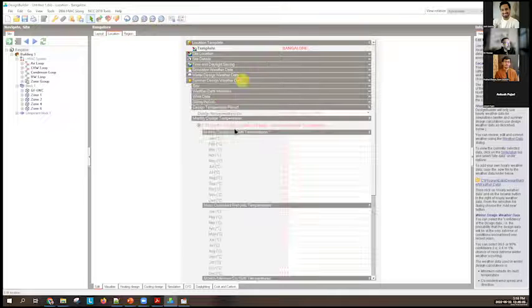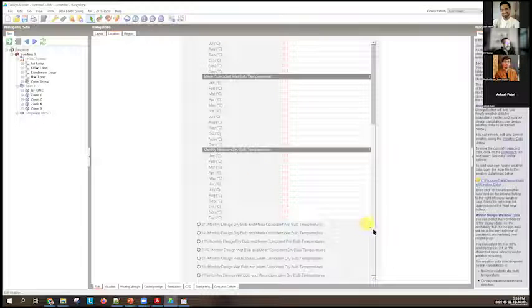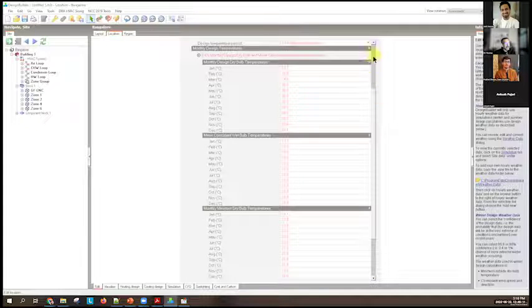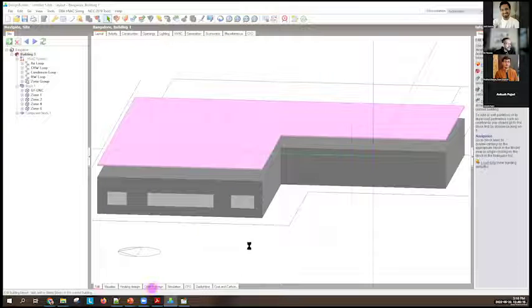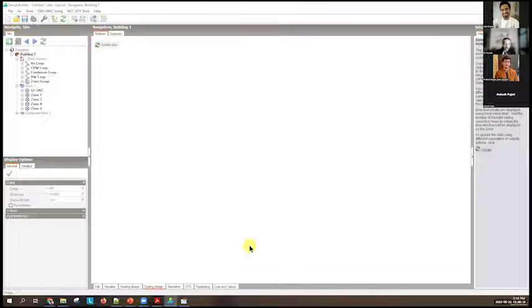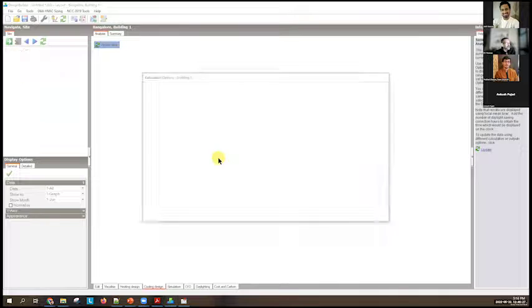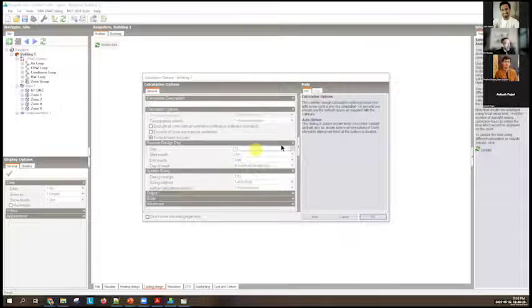So your summer design data you can choose, and there are options that you have to understand which options to choose. And then you can run a cooling design as long as you've got all your internal loads set, your thermostats are correctly set, all of those things are done. You can actually run a cooling design calculation. I'll change the oversizing factor to 1.